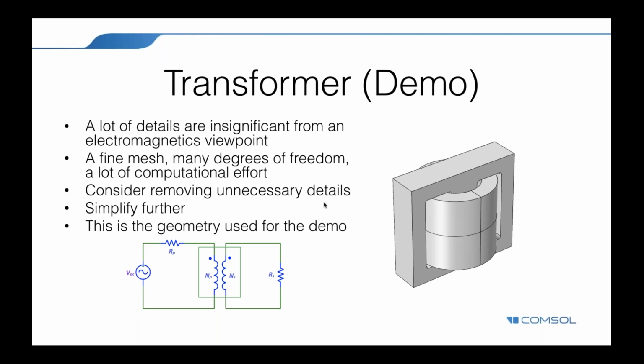The model assumes that the primary and secondary windings are made of thin wire and have multiple turns, using the assumptions that the wire diameter is less than the skin depth and there are many turns. These windings are modeled with the Coil feature. Furthermore, the model does not account for eddy currents in the individual turns of the coil.